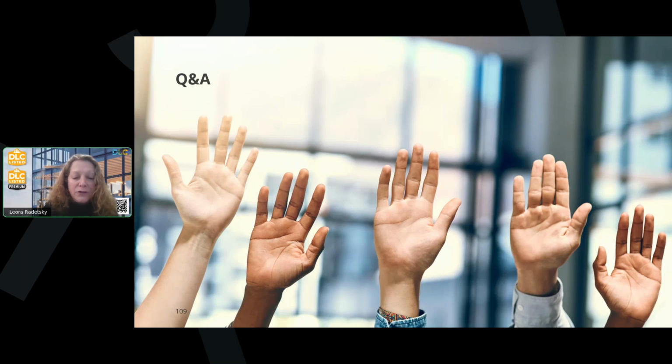So if there's any questions about that, you can email us and we'd be happy to discuss. If it's future capabilities we have to think about for a point revision, we can certainly do that. But I believe we have provided a pretty reasonable way to allow those products to be used, not just for LUNA, but also for SSL V6 if you'd like to use filtered amber LEDs. The only PUD that filtered amber LEDs cannot be used for is turtle lighting. And PC amber LEDs cannot be used for that either, only direct emission amber LEDs.